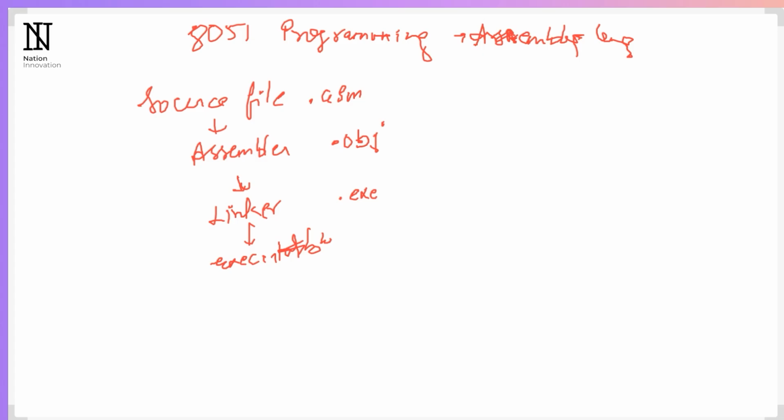So the assembler converts the assembly language to binary language and then stores it in the microcontroller memory to perform the intended task. Now 8051 has CISC type of architecture, that is complex instruction set architecture. It is based on Harvard architecture and it has certain peripherals such as 32 input output pins, timers and counters, serial communication and memories. And registers are the main part in processors and microcontrollers, contained in the memory, that provide a faster way of collecting and storing the data.